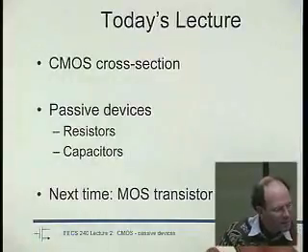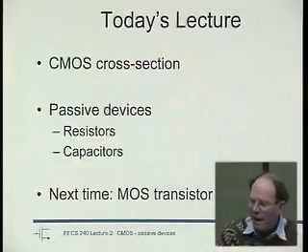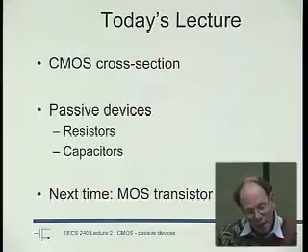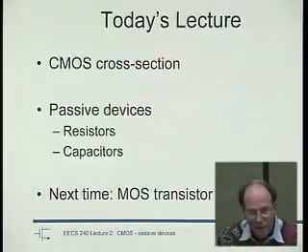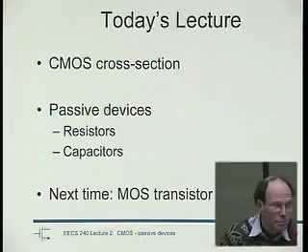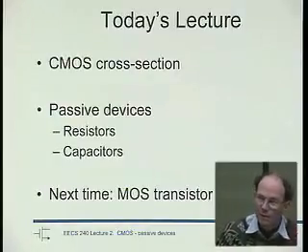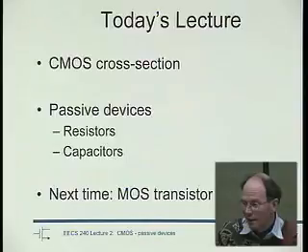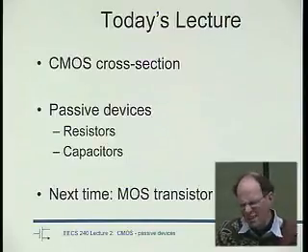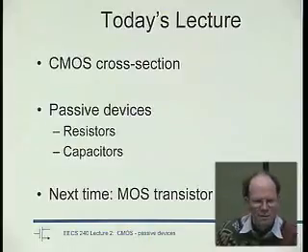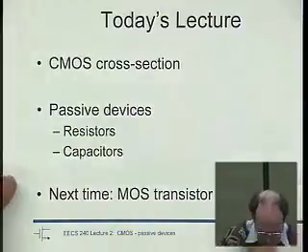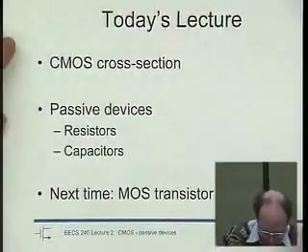Well, what is it that we may also have there in our circuit that SPICE doesn't even know about, and consequently could make a difference between what SPICE thinks the circuit is going to do and what reality is? And you won't be surprised if I say that most of the time the reality, unfortunately, is not quite as good as what SPICE says. So SPICE is a good check, but it's not an insurance, or certainty, right?